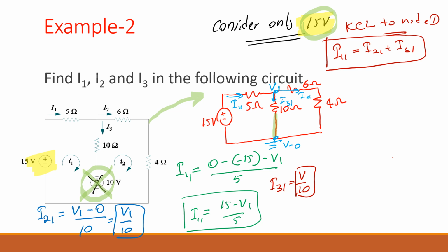Yes. So now you have just one source, so the circuit is easy and simple. We are finding the three currents, I1, I2, I3, only if we have 15 volts. You can use any method you have learned so far, but in this particular question we are using the node voltage method, which we did last week. Remember that?